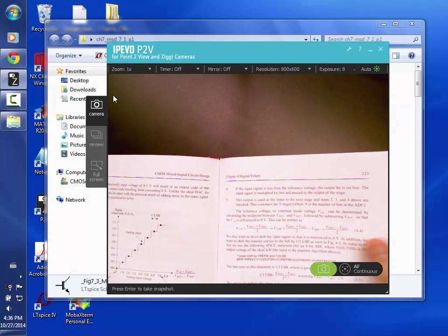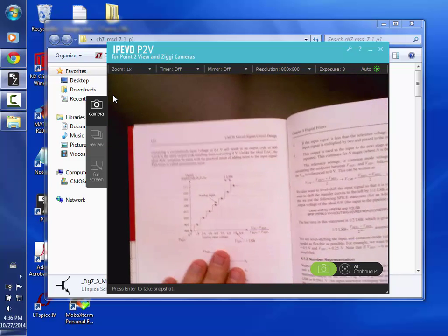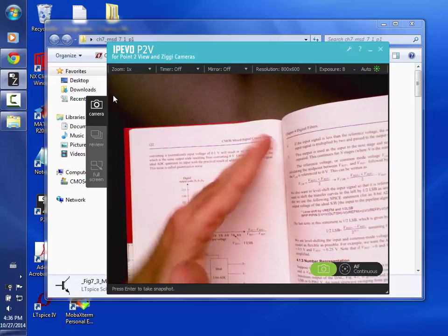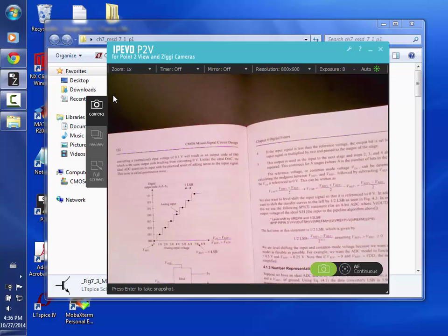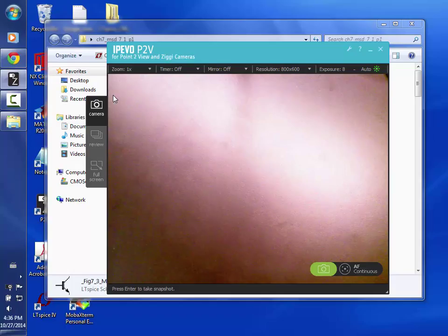Yeah. Well, more filtering, and here's the plot, but you can basically imagine if you look at the slope as being the gain, you have much less variation if it's a multi-bit versus a single bit. Okay, so you have problems there. Okay, so let's go talk about digital modulator. Are there any questions on that? Okay, so the digital modulator